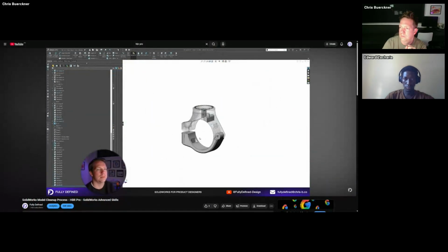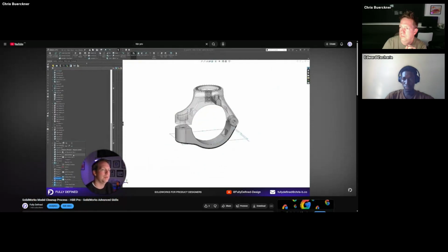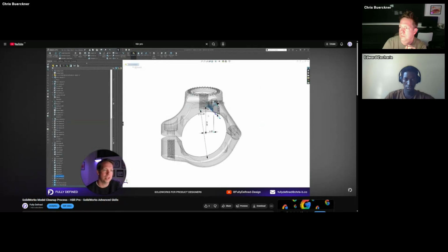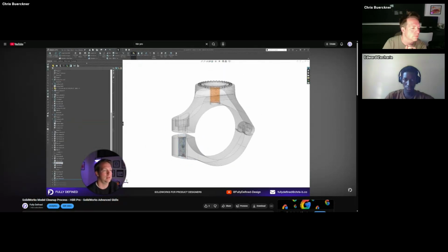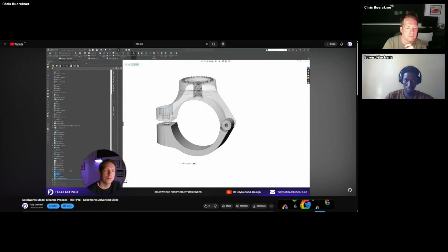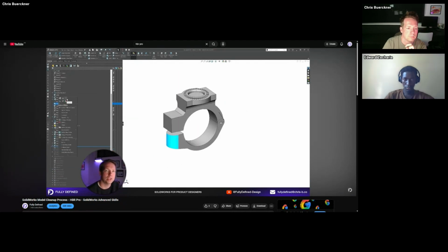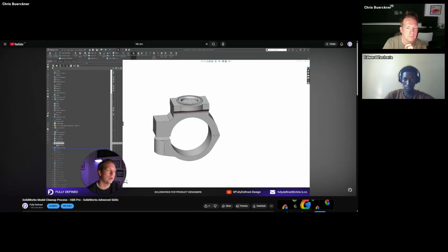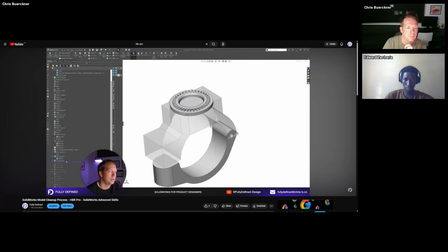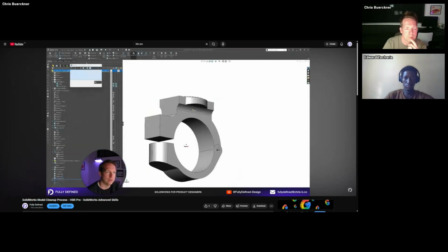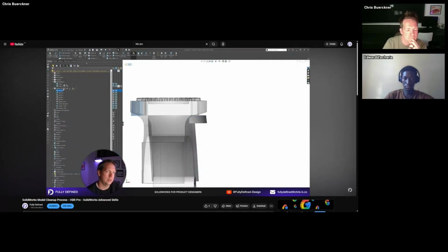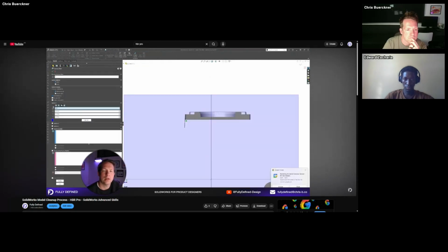My aim is to maintain the geometry, but clean up the model. We're doing this to make it possible for others to use this model and make changes in the future with minimal fuss. That means removing obsolete features and sketches, moving the driving sketch to the top of the feature tree, or in this case, actually creating a driving sketch, and reordering the feature tree to group associated features into respective folders. As I start this process on this model, I was moving up and down the feature tree to learn about the model and inspect the features that I could do something with.